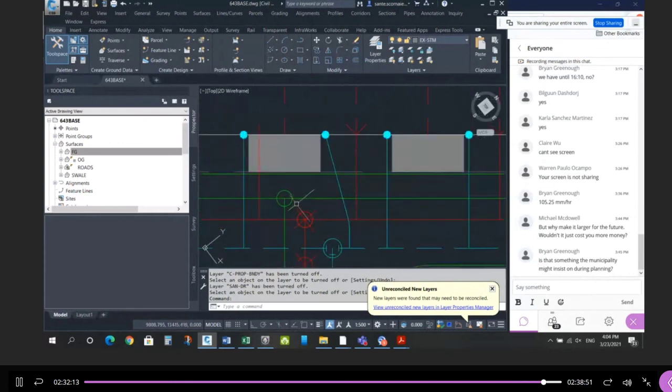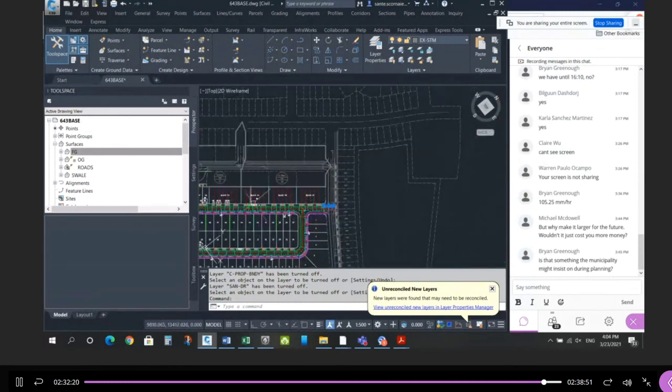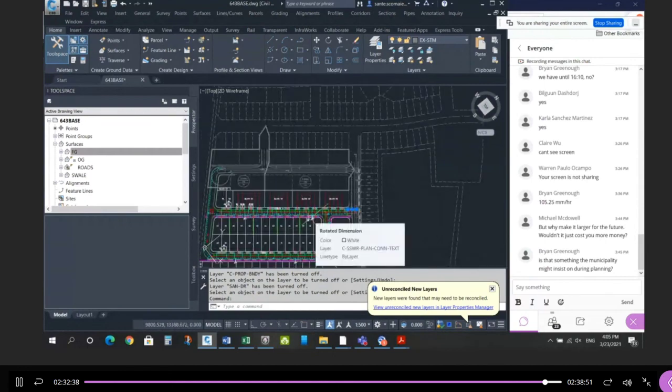And then whatever you get here for an invert, add the minimum drop for straight through, add the minimum drop for 90 degrees, and then you do the rest of the two legs together. So storm is like I taught it last semester. Start at the bottom, use minimum drop, minimum slope, and go uphill. Sanitary we did backwards for a different reason, because this pipe here is already deep enough, so I don't want to make the system too deep. Storm is much more shallow.